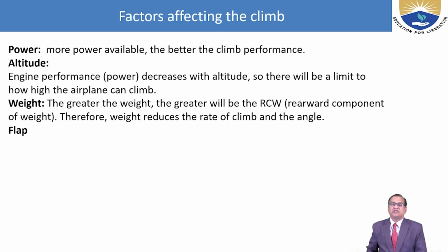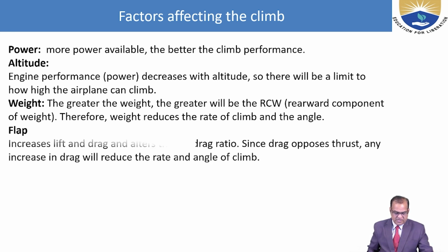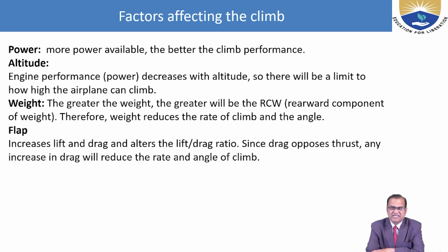Now flaps. Flaps are lift producing devices. Additional lift is provided by the flap. So flap increases the lift and the drag and alters the lift to drag ratio.